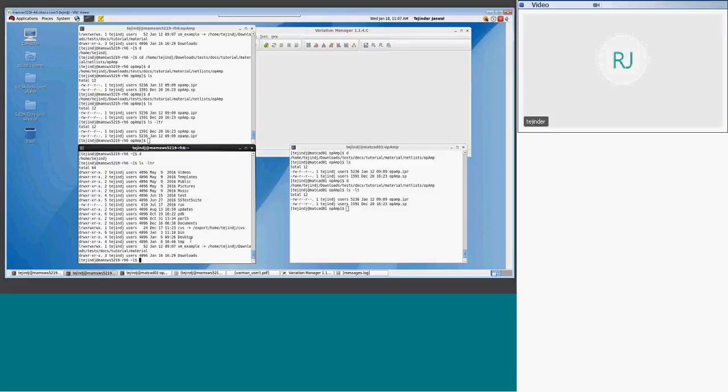It is formed into a matrix, and depending on those calculations, it runs the simulations, minimizing them. In XFAB there are many corners; if using TSMC and others, they probably have more variations. It reduces the number of simulations with the same accuracy. That's the proprietary algorithm, but I cannot comment on that.